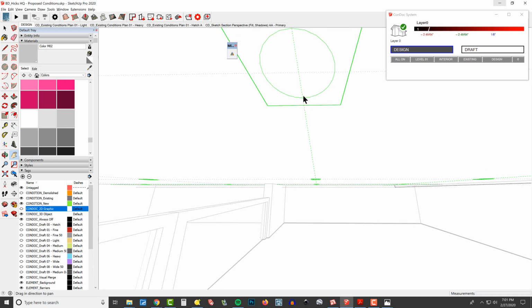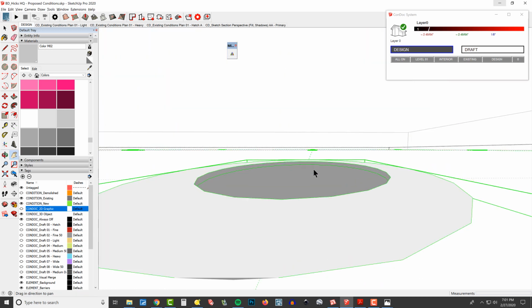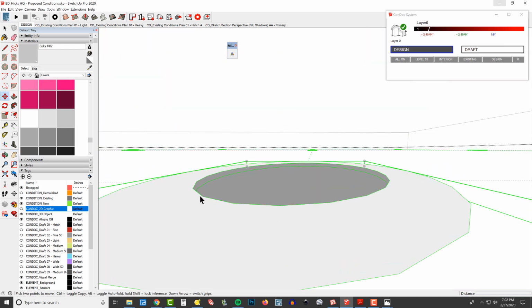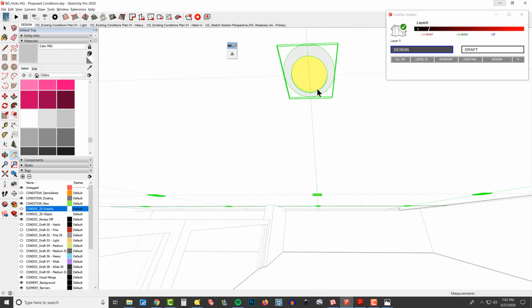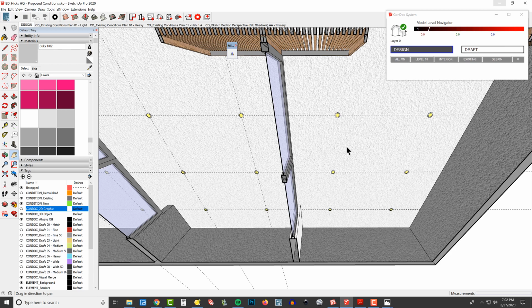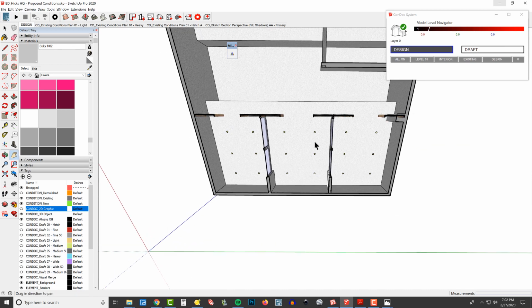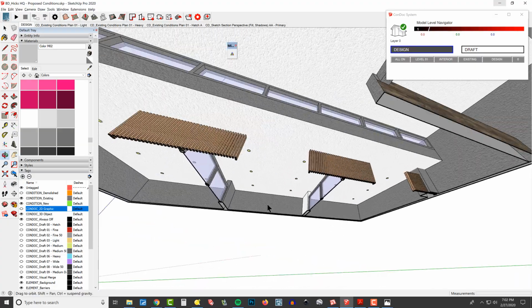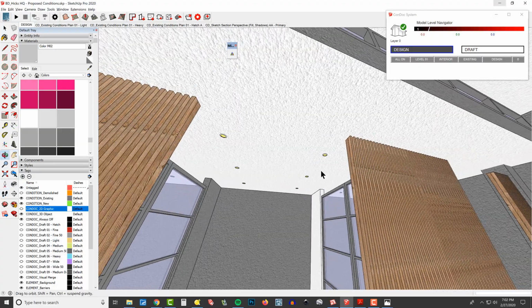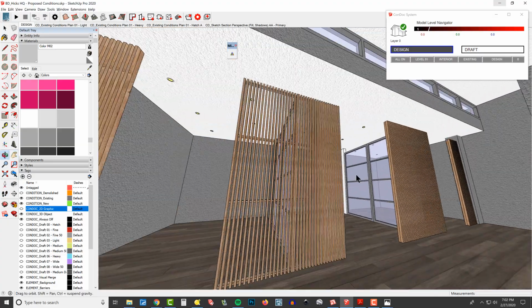All right. I'm going to select everything, and because I'm in this group, let's scoot this stuff down. Tap the up arrow key like that. All right, now I can back out of here, hit Control E, clear my guides, and that would be a cool lighting plan for in there. My other keyboard shortcut is F5, which releases that section plane.